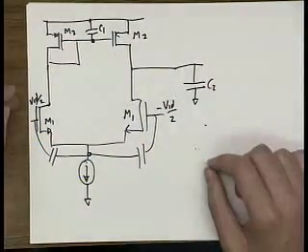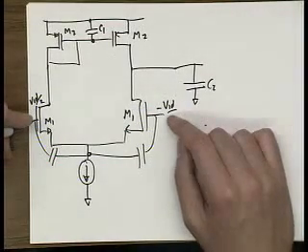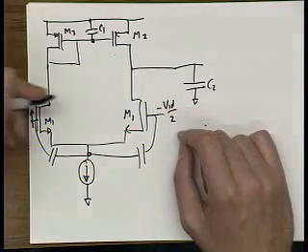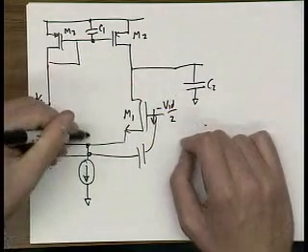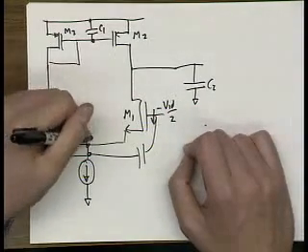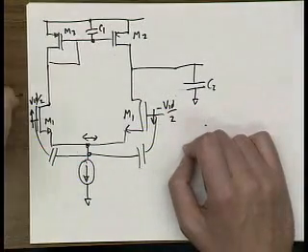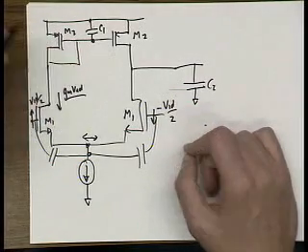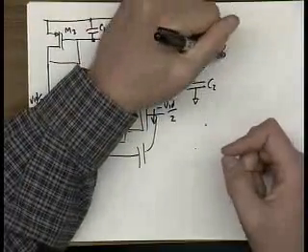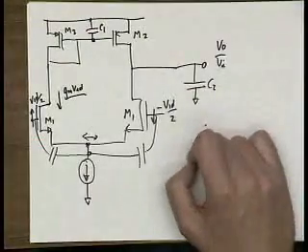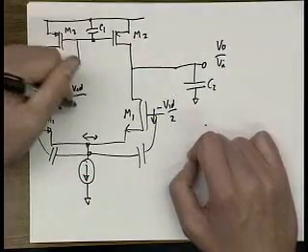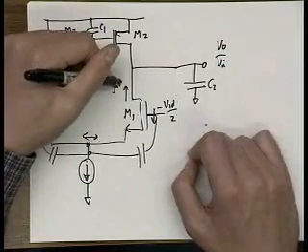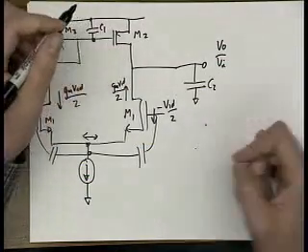Okay? So let's assume that this is driven by perfect voltage sources, so there are no poles at the input nodes. This goes up, this goes down. We know this node is going to stay a virtual ground, so it stays basically the same. As a result, GM VID flows in. What we're trying to figure out, I'm sorry, is V out over V in, as per usual. GM VID over 2 that way, and so small signal you get GM VID over 2 that way.